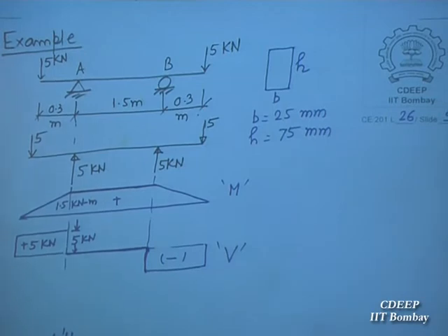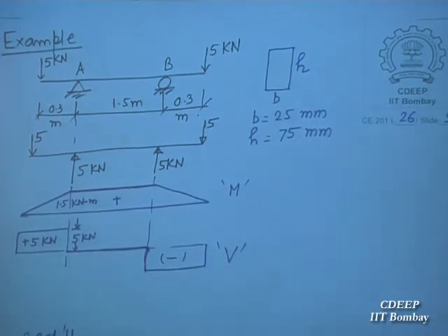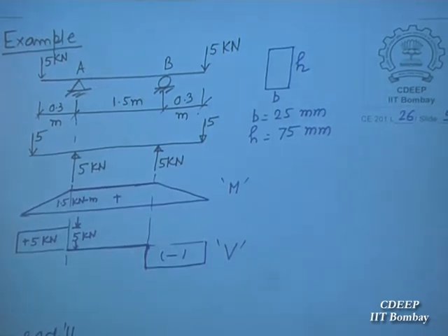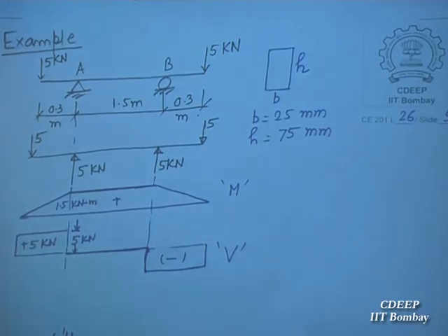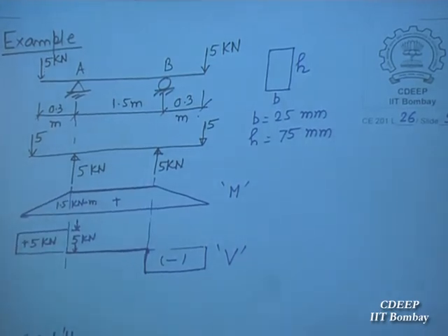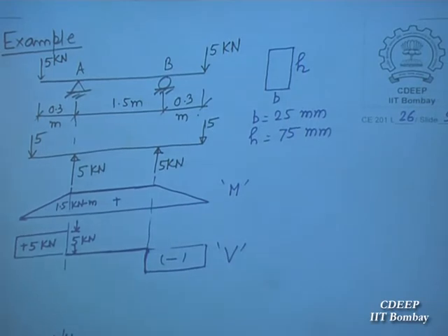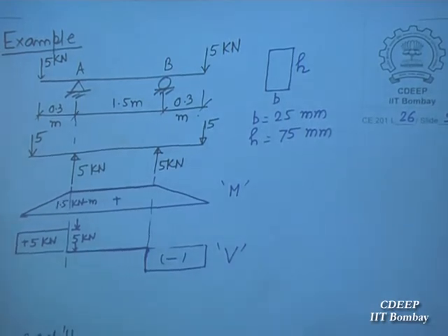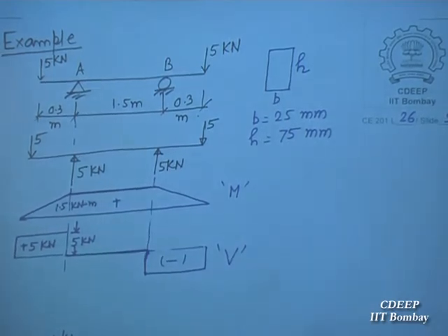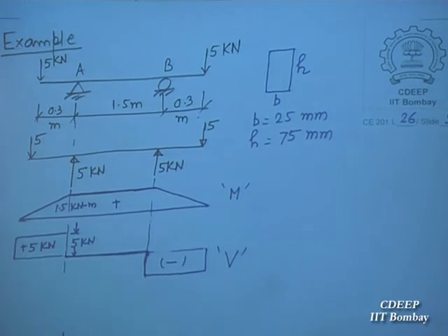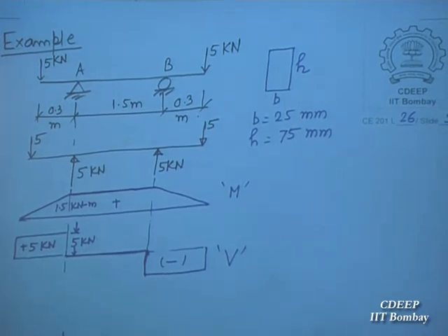So for example, for steel, it is about 1.5. For concrete, how much is it given? Anybody? 3. Factor of safety is 3 for concrete structures, because concrete is a very complex material. You manufacture concrete on the site with labor, they are unskilled.